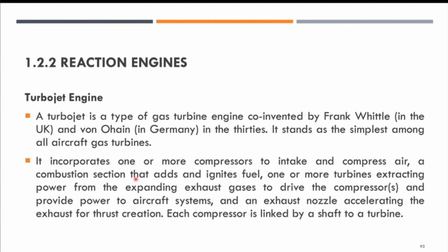So it incorporates one or more compressors to intake and compress air, a combustion section that adds and ignites fuel, one or more turbines extracting power from the expanding exhaust gas to drive compressors and provide power to aircraft systems, and the exhaust nozzle accelerating the exhaust for thrust creation.